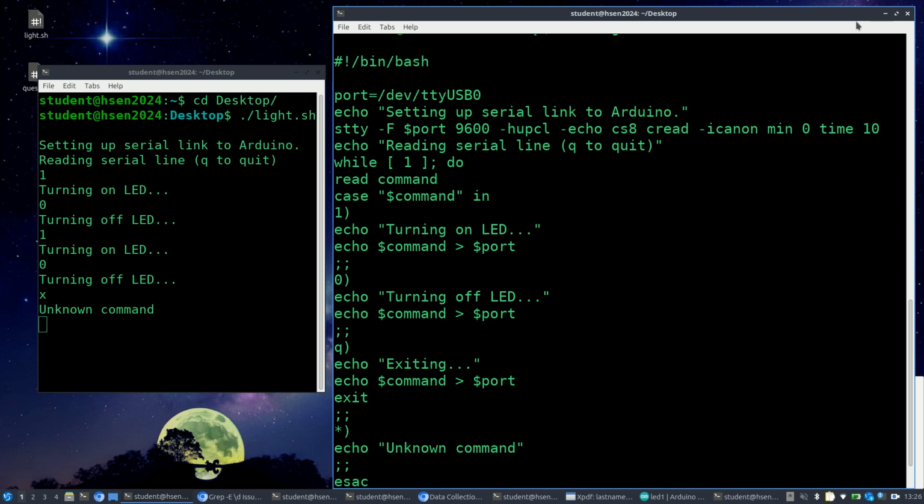The thing is, every time that you start a communication, if the other one doesn't work, it's better to exit the communication first and then try again. Otherwise you're going to say, oh, your Arduino is not communicating, and then you unplug, and when you plug it back in, guess what? It's going to be USB 1, because it's going to keep taking a USB 0 placement on your USB. Page 0, yep. That's good.